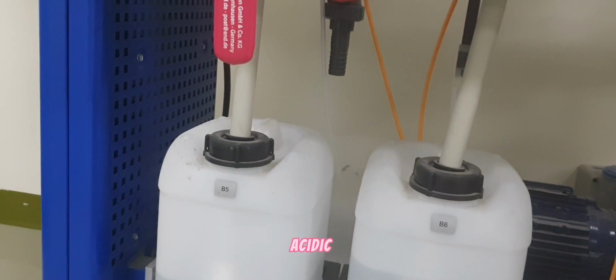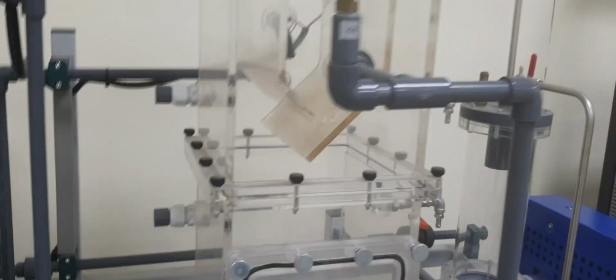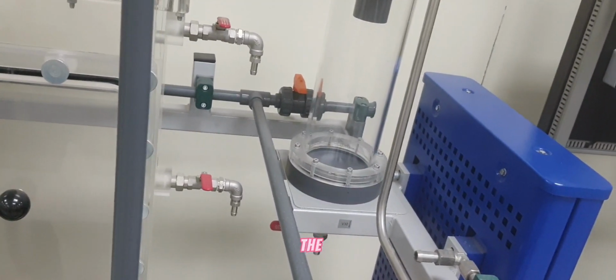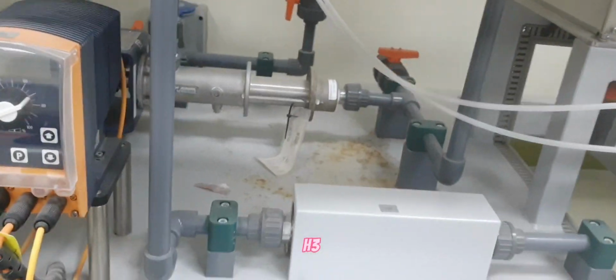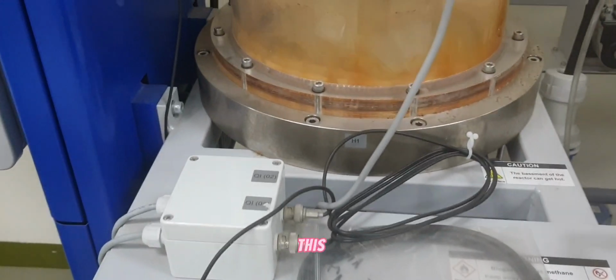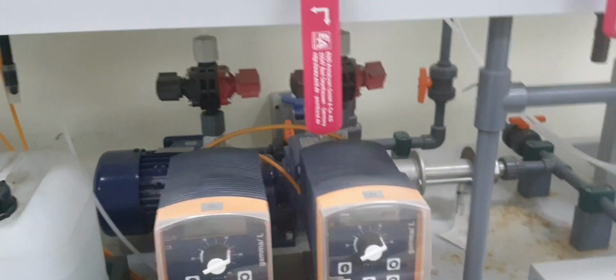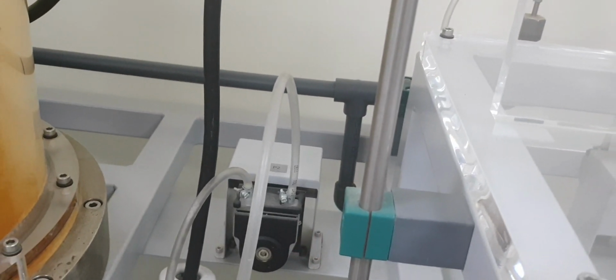is my acidic tank, and B6 is my caustic tank, and B7, which is here, is my UASB reactor, and B8, which is here, is the foam reactor, and H1 and H3 are my heaters. This is H3 here, and H1 is this one, and P1 is my raw water pump, which is here. P2 is the return sludge pump, and P3 is a metering pump, which is probably